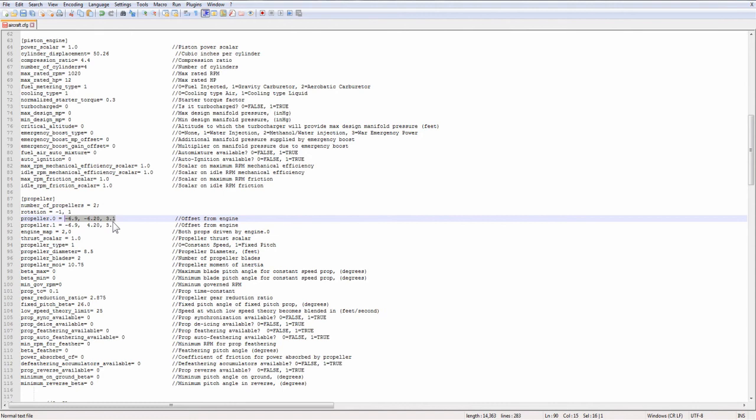The reason being is because if you look at the Osprey, if an engine failed on the Osprey, you wouldn't be able to survive an engine failure in that aircraft. It needs both props to function in order to even fly. So that is how that works. So quick repeat: prop number, position relative to its engine, engine map. The position of the number in the map is the prop, and the number itself is the engine. So the number can't be higher than 3 because you can only have 4 engines, but you can have however many positions that you have props. I hope it didn't confuse you too much. I hope that makes sense, but that's how that works.